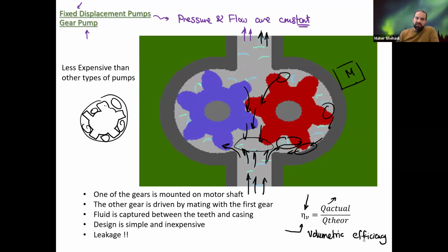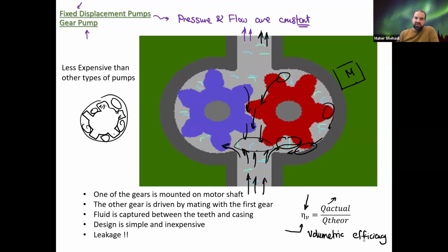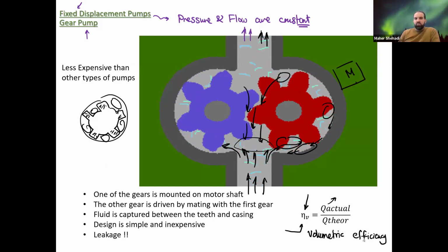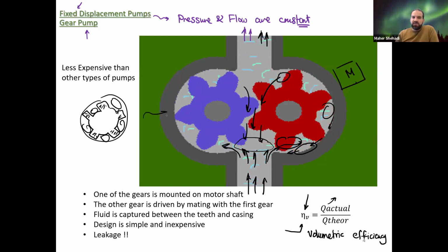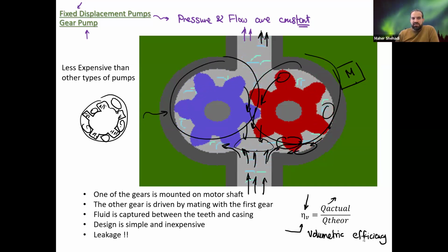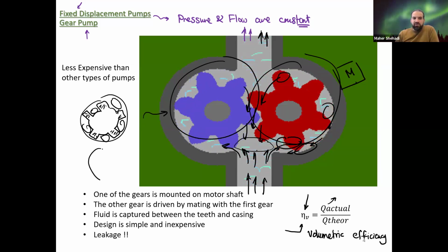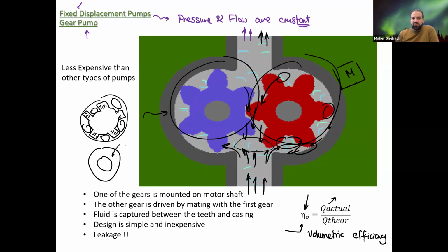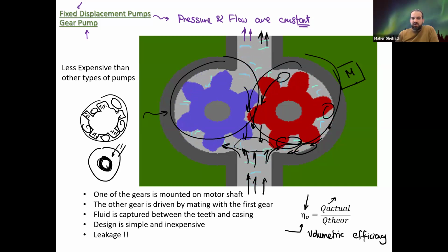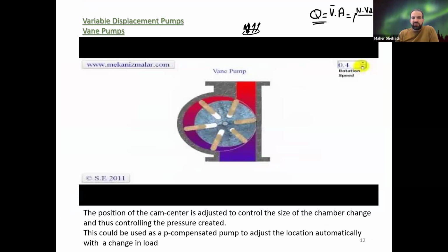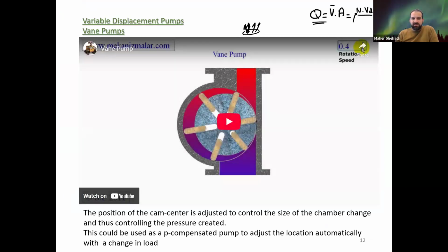If we assume it's about half between the gear volume and the empty volume where the fluid will be rotated, what's the total displacement for this gear pump? Remember, we have one here on the right and another one on the left. If it's half, then the total would simply be this area here. So it's pi over 4 d squared minus pi over 4 d squared, or pi over 4 times d outer squared minus d inner squared. That's actually the easiest one to calculate.